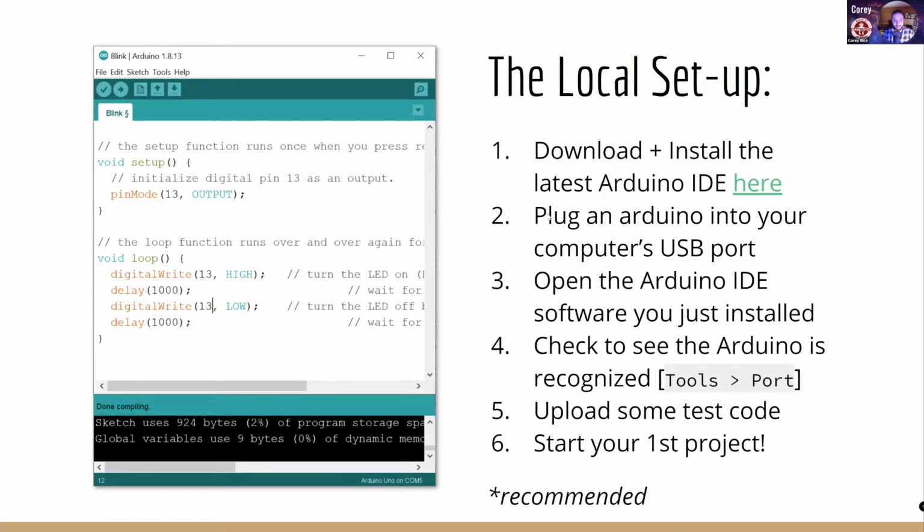The second thing you do once you download and install the Arduino IDE is you plug the Arduino in, you open the software, and you make sure that it's connected. You go to the Tools area and you connect to the port the Arduino is physically plugged into. From here, you write code and it just works. The Arduino IDE can be really helpful. It can also be frustrating. You've got to make sure that the drivers go in as it works.